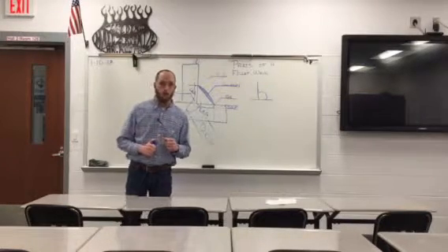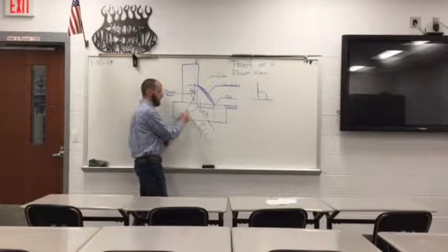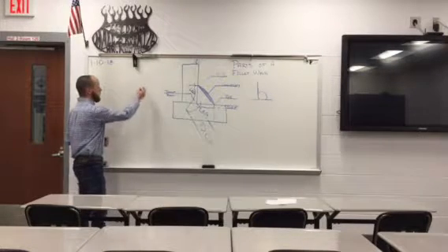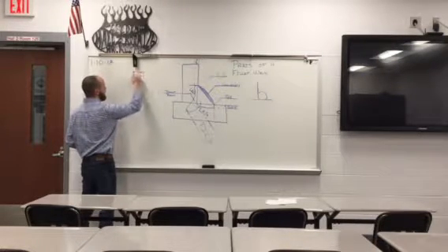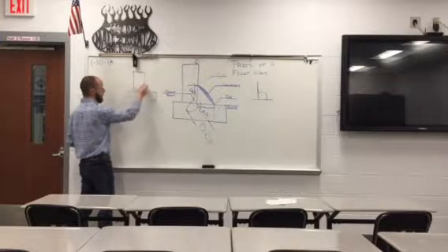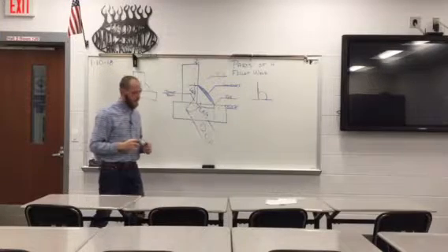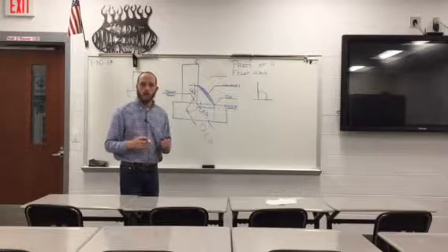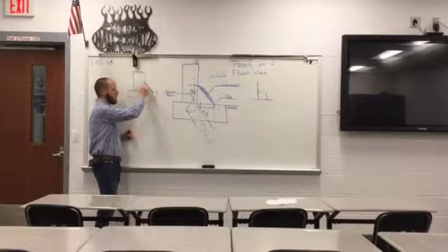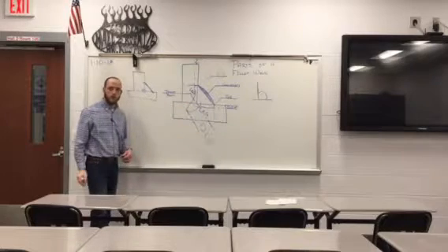Now, we're going to discuss the throats of a weld. There are three different throats. And like I said, the throat is measured 45 degrees out from the joint root. The first one we want to discuss very briefly, one that is very seldom referred to, is the theoretical throat. That's theoretically what a weld should look like. That's measured from the face of the weld without weld convexity to the joint root.